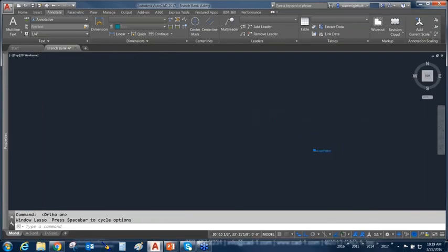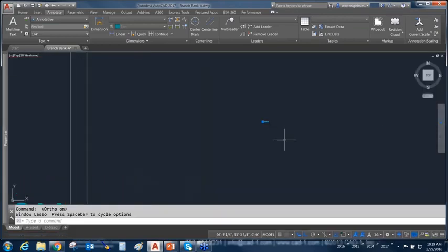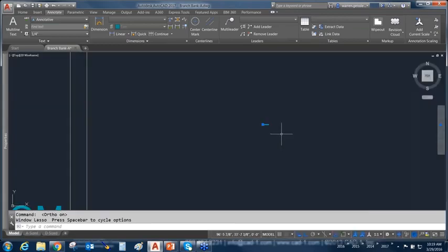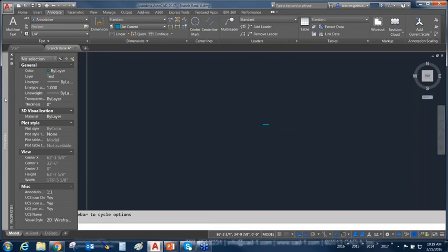We're not going to print drawings at 1:1. So how do I fix this? Well, there's a couple of ways to fix annotation inside your current drawing. Method number one is you get to use the AutoCAD Properties window, which I've got anchored over on the left-hand